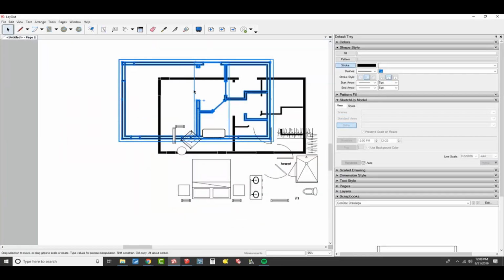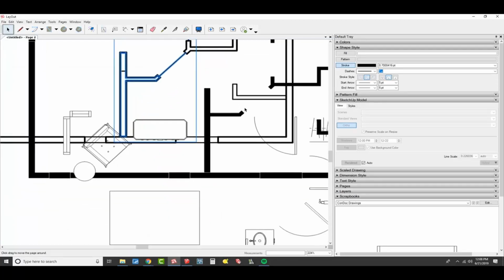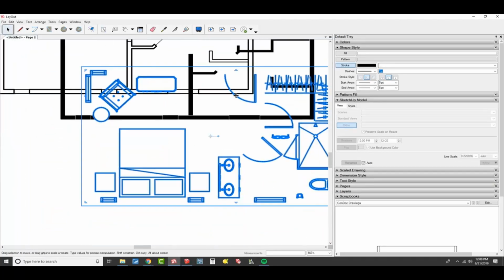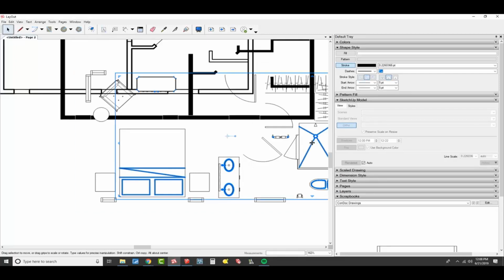We don't really care. I just want to get to the line weights. So the thickest line weight that I have is going to be a 2.1, and then we go back down to like a 1.4, and then we've got a 0.7, and then we've got a 1. Let me ungroup this as well. Then we've got this guy is going to be a 0.45, and then this guy is going to be a 0.22.